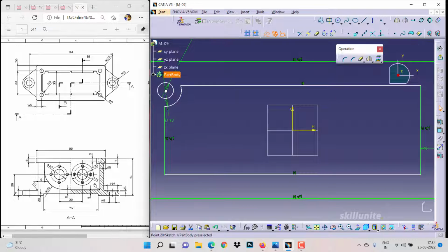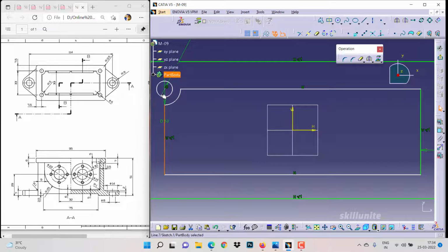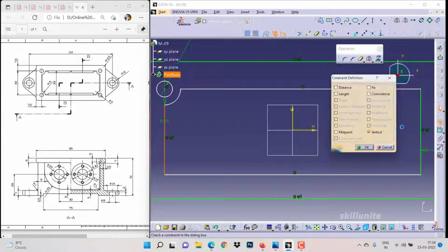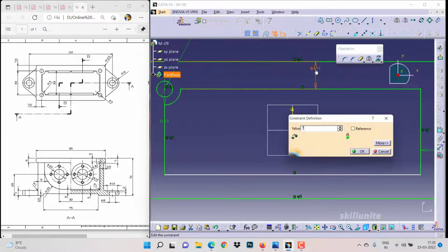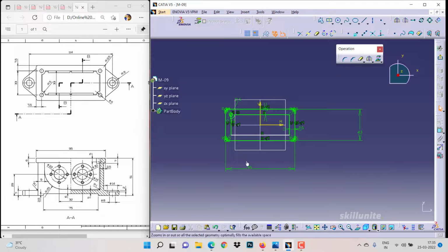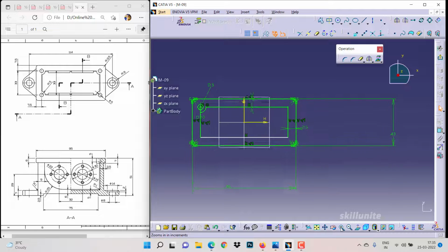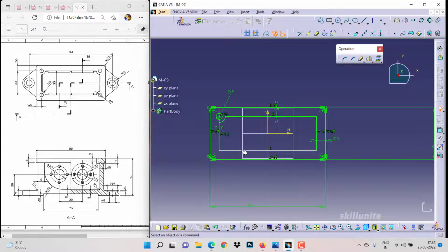As you can notice the circle is moving up and down, so it has to come exactly straight with respect to this. So let us make it coincident. Similarly this also needs to touch straight. Here also we need to make coincidence, and the distance that was deleted, that's 7.5 mm, we'll keep that, so automatically it becomes fully constrained. Now either we have to mirror or create a pattern. Let us do mirror, that will be easier over here. So this also maybe I'll give distance.